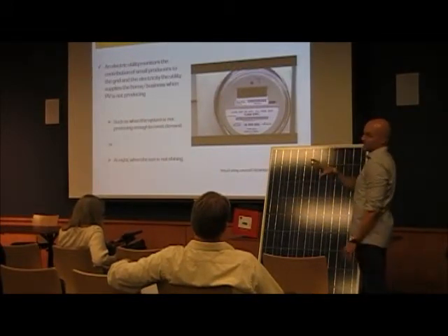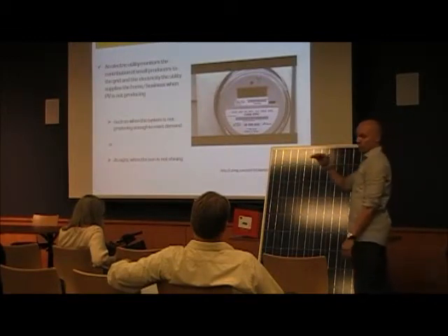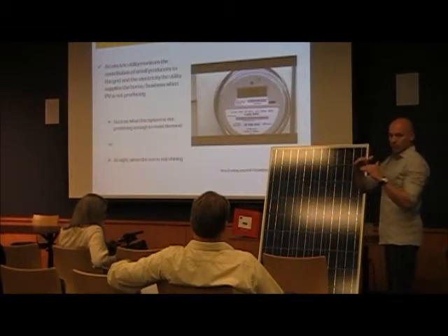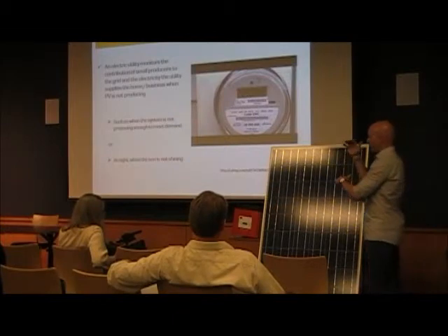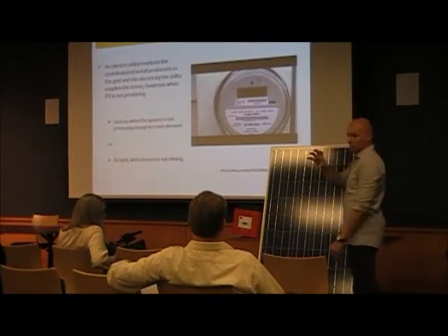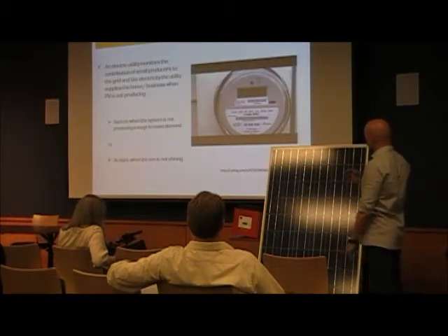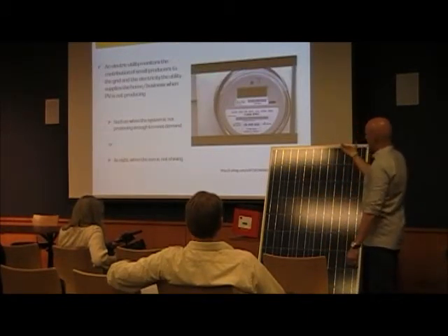When we design these systems, we always design them to push out less than 100% of what you're pulling, because once you go over 100%, then the utility buys it at a low cost. Like 2 cents, or in Alliance territory, 6 cents. Whereas if you sell back at what you use, or just under what you use, then you can sell back for the retail rate.